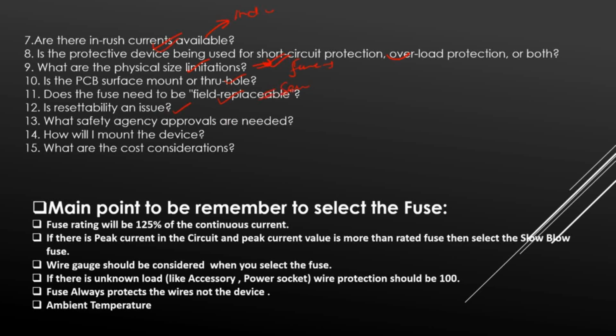Is the resettability an issue? What safety agency approvals are needed, like ISO standards? How will I mount the device, and what are the cost considerations? So all these factors we have to consider when we are selecting a fuse.